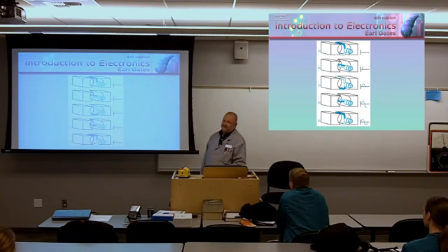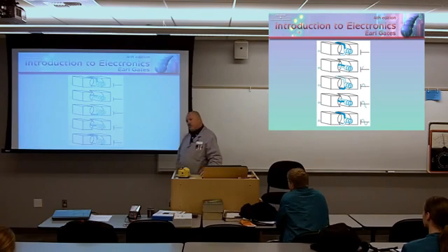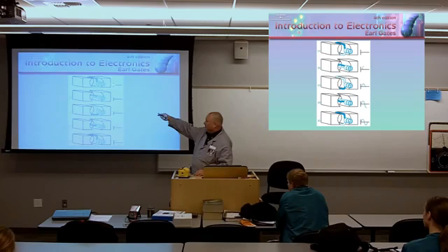Parallel. It's right at the top. You see how it's right at the apex here, the top? So right at this moment in time, it's parallel to the lines of flux. How much current do we generate when we're parallel to the lines of flux? Faraday's law. How much? 0. And look what we're generating right here. 0.